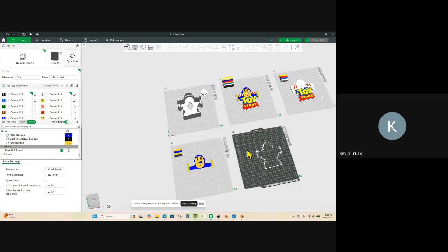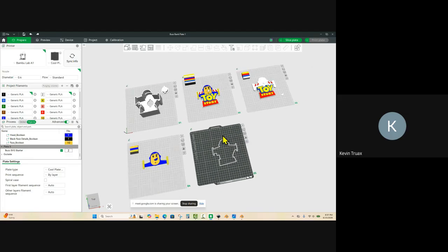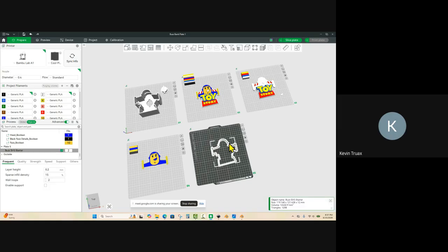So then all we need to do, now there was one other thing in regards to this flange. We made a slot on the back side of our plate. It might be helpful to take our flange and make a little adjustment in the XY compensation. So if we're here on our objects tab and we have our flange selected, we'll go to the quality tab, and we're just going to make this a touch smaller right here. XY contour, let's make it a touch smaller, -0.3.